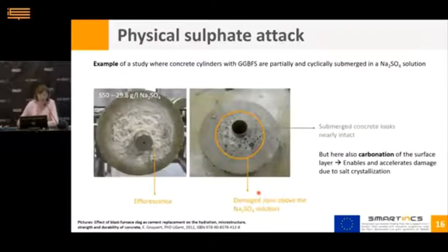In my PhD, I was also looking at what happens with my specimens, now with our concrete specimens, when they are exposed to partial submersion and also cyclical submersion. So what you here recognize is probably what you have seen this morning in the presentation of Professor De Belie, where she showed the same type of equipment that was used for acid attack, but here the concrete wheels, let's say, turn into a sulfate solution. So part of the time they are immersed, part of the time they are not immersed, and here the middle zone is in fact never immersed in the sulfate solution.